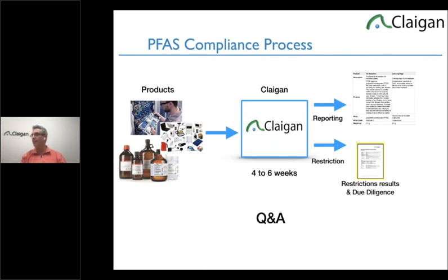Now, would these essentially not be applicable to articles like tents and outerwear? Though there are sector specific sides, like waterproof clothing, which depending on the wetness level will have PFAS restrictions, it may be a bit foolish, because you can make those coatings without the PFOA families. A lot of the outdoor fabrics with fluoro coatings were found to have PFOA. They can be made without it quite well. The problem with the replacements is they can be quite water repellent, but they're not nearly as stain repellent, and they can stink and discolor and all the bad things in life.